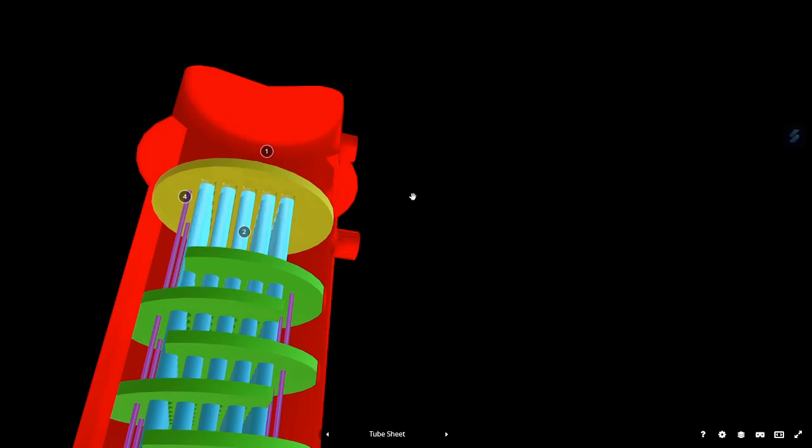How does it help? When you have a hairpin heat exchanger, the area required is very large, and another important aspect is the leakages. Here you can see the leakage points are pretty well covered because these pipes are grooved inside the wall, and they are packed in such a way that they don't leak. In hairpin kind of heat exchangers, there are a lot of leakage points.